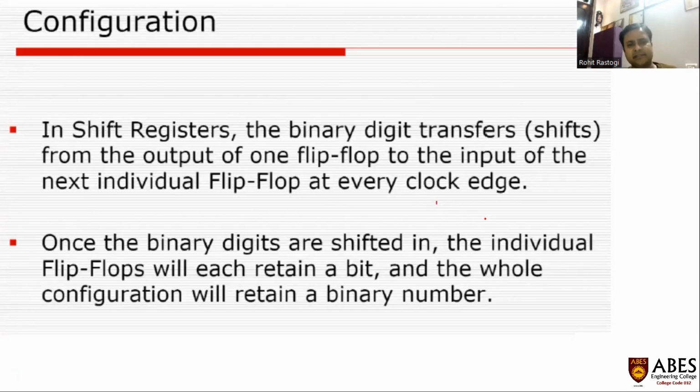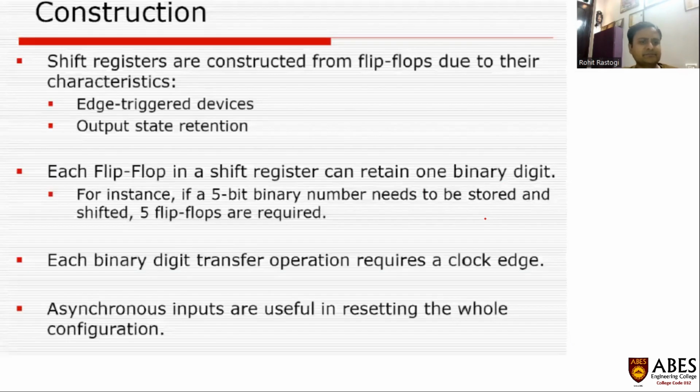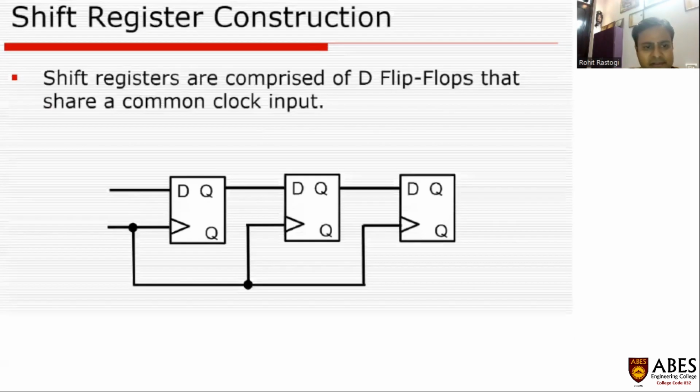Here you can see that a shift register is designed with the help of flip-flops, because a flip-flop can store one bit of information. So shift registers are constructed with different flip-flops. It may be edge-triggered flip-flops or output state retention flip-flops. Each binary digit transfer operation requires a clock edge. Asynchronous inputs are useful in resetting the whole configuration. To generate synchronization, we have to keep the clock pulse the same, and if the clocks are different, they will generate an asynchronous operation.